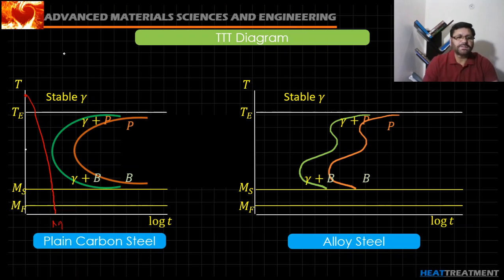We can describe it as: easier for quench means high hardenability. This means that if we have more allowance or we may resort to a low rate of cooling, it means we are having more hardenability.